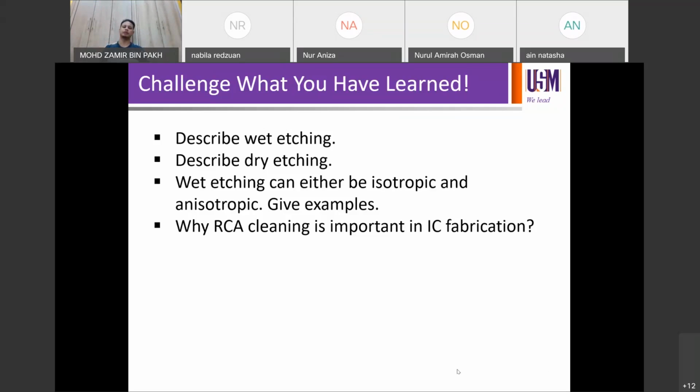But usually the common system we use is vacuum, down to 10^-5 torr, for example, and then you inject your argon, then initiate the plasma formation, and then you get the plasma inside the vacuum chamber. But there are cases where you can use plasma at atmospheric pressure. We have that system in our lab. We call it APCVD, atmospheric plasma chemical vapor deposition. We will discuss that when we talk about thin film deposition, maybe next week or the week after.